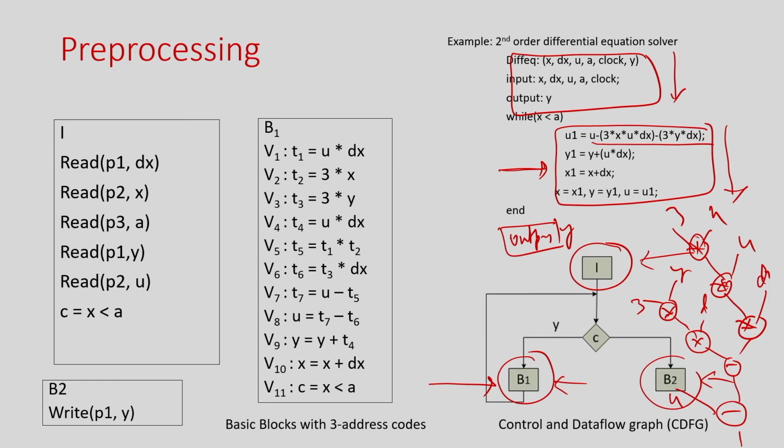But in hardware I have to execute this in hardware, right. So, suppose you make these connections like this. You add multiplier 1, 2, 3, 3 multipliers, and then these 2 multipliers in parallel. Then there are 5 multiplications followed by 2 subtraction operations going to happen just to execute this, right. And it has to be completed in a single clock, because within the same clock, in this time frame, all these operations have to be executed.